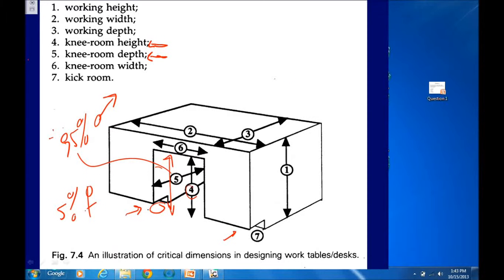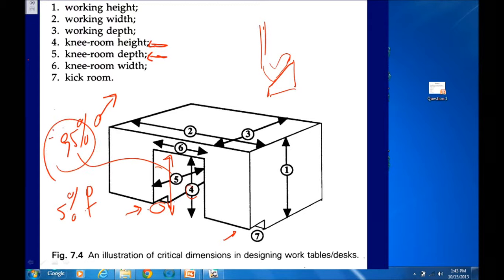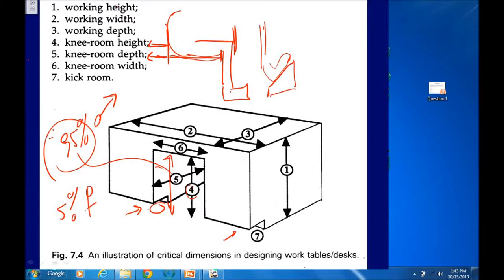And the reason for that is that I can accommodate that female then with a footrest, right, to bring them up to where they need to be to accommodate this taller individual right here to be able to fit under this. But the other thing is that knee clearance, right? Being able to have that knee clearance in front. So now instead of looking at the popliteal, right, which we were doing for the height of the chair, right, the seat pan, we're now looking at this clearance right here in terms of where that threshold is on the desk on how far in they can go.